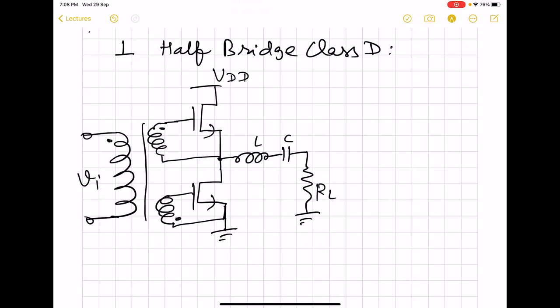So here note down the polarity of the transformer, and the winding in the primary and each of the secondary are equal. So this is how we define the VGS, voltage of gate with respect to source. This has to be kept in mind so that we can correctly predict which of the MOS is on or off. So we have two MOS, M1 and M2.